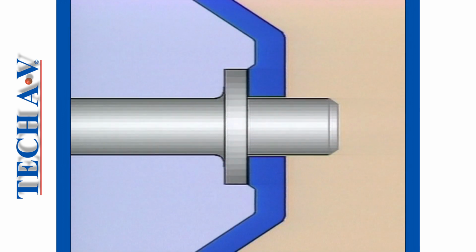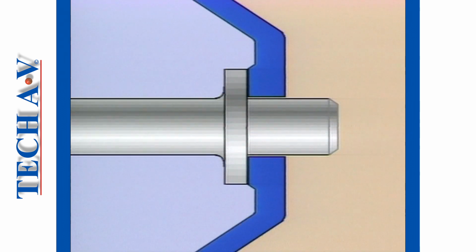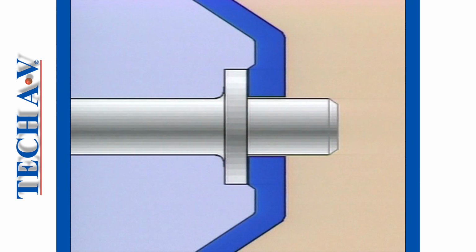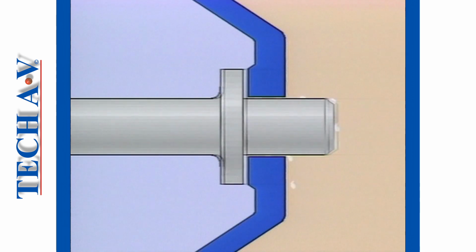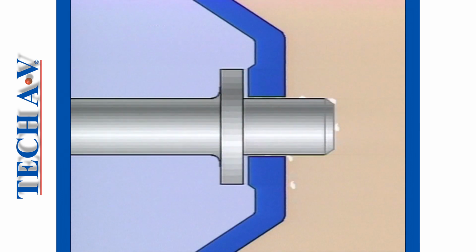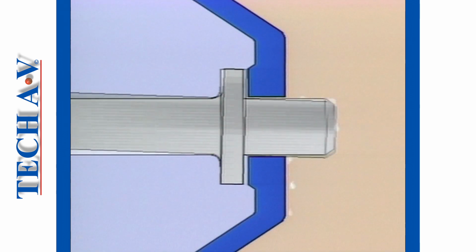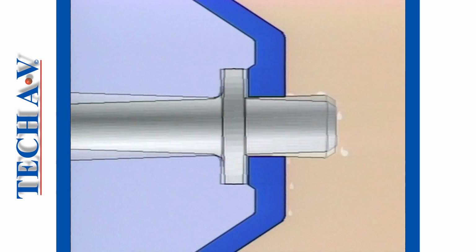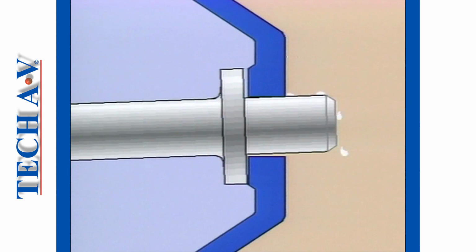Early attempts at producing maintenance and leak-free seals began with engineers designing an end-face type seal that relied upon a shaft shoulder running up against a machined housing. The design was by no means perfect, as no allowance was made for shaft end play or axial float, which meant that the seal was broken and leakage occurred each time the shaft happened to float back. Further, no allowance was provided for any shaft whip or runout, which inevitably occurs. This too prevented effective end-face sealing.